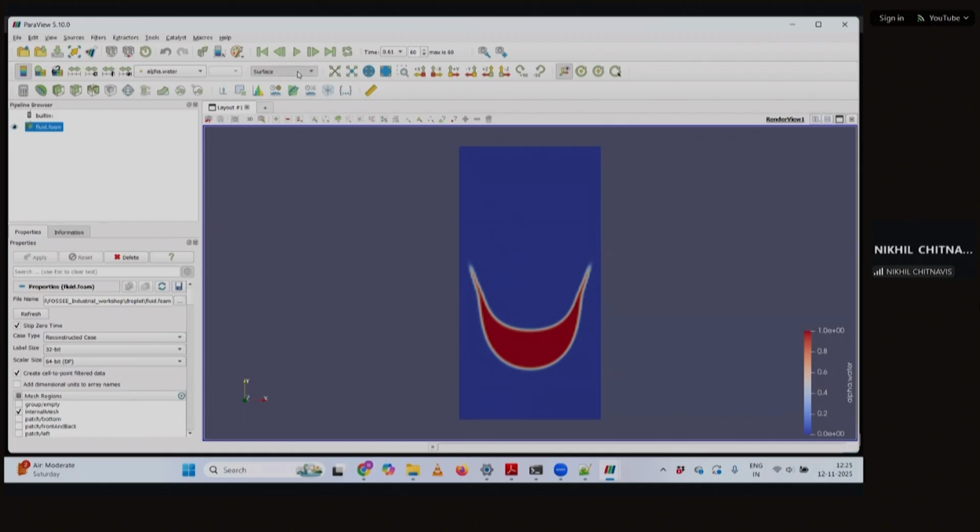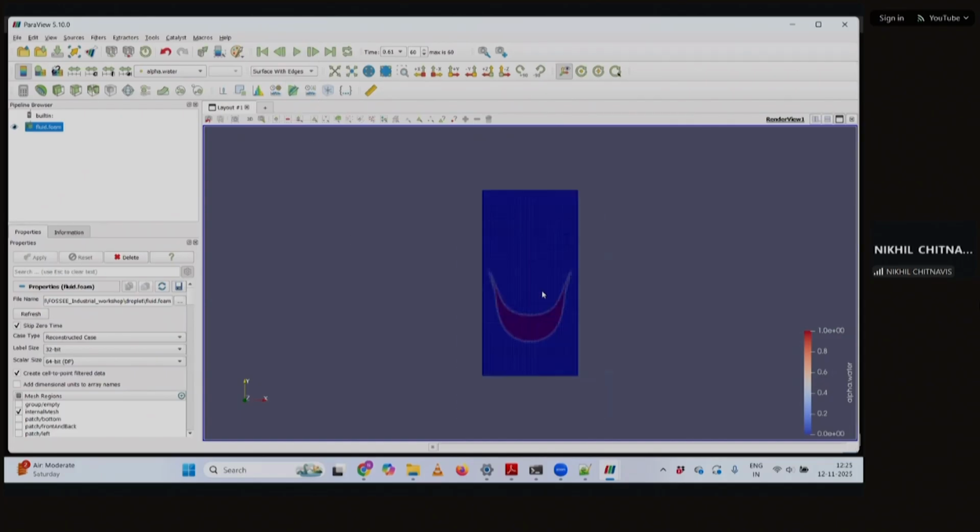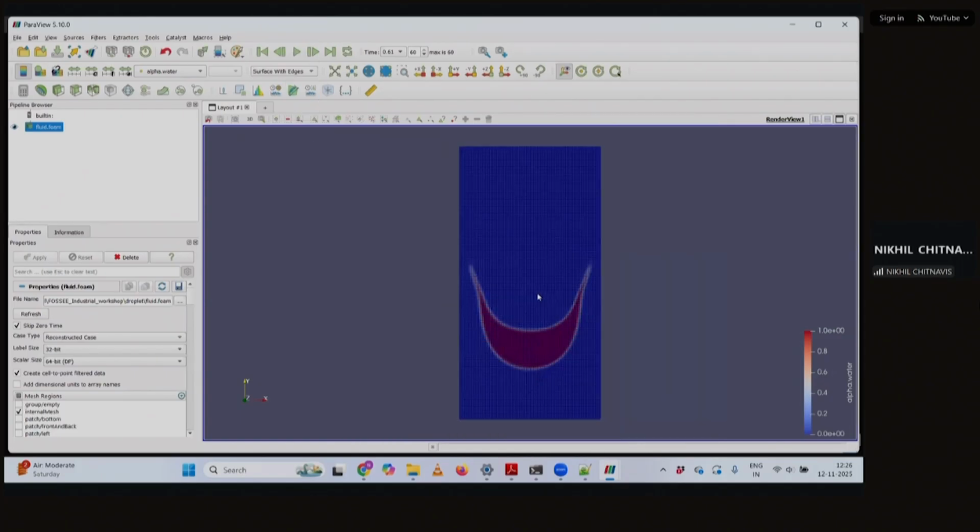Now, in both the cases which I've shown, that is the bubble rising and the droplet case, our mesh is not changing. And also, to capture the interface, we require this fine grid all over the domain, which is not required sometimes because we are only capturing the interface. But what about this portion? Here, this much refinement is not required, which will anyhow increase the computational time.